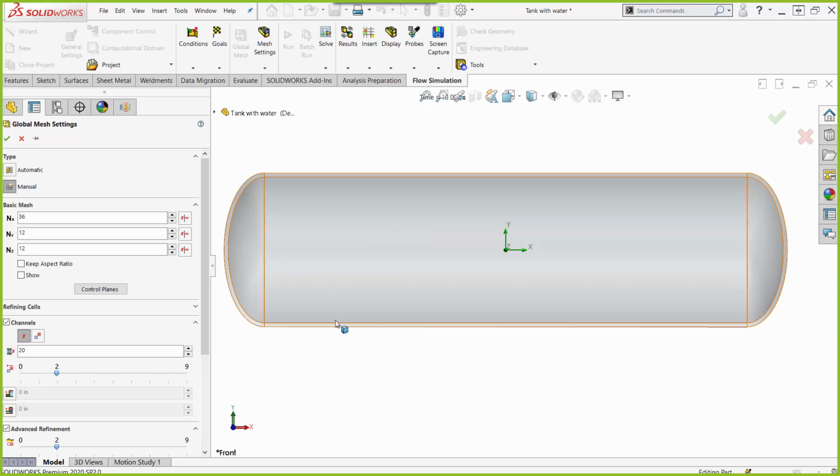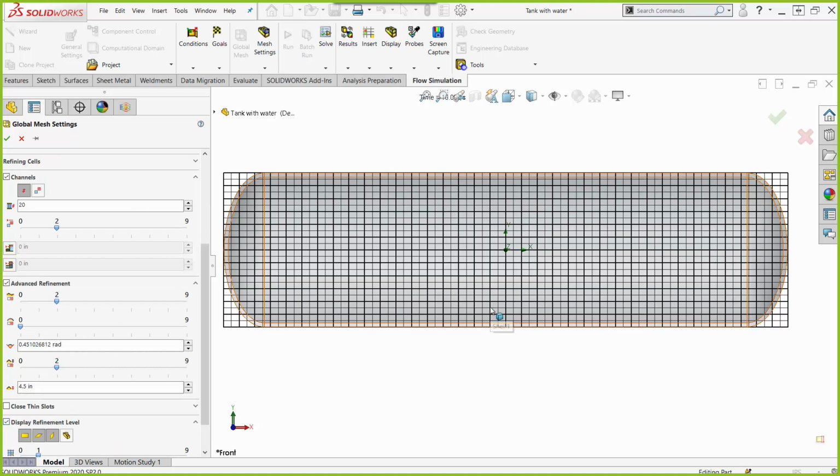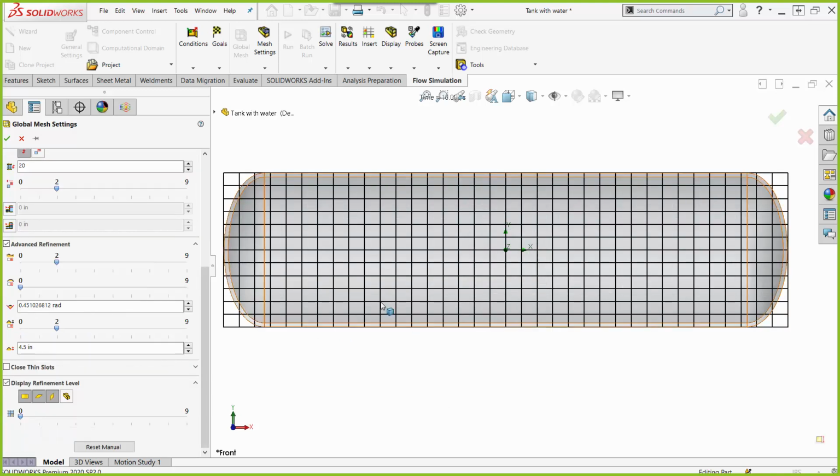So for accurate answers, I need a good representation of the volume of the fluid, right? That just seems logical. If I have fluid cells that are too large, I'm not capturing that interface or that free surface very well, and so I'm getting a very blurry, strange kind of result. So it is recommended that you do refine anywhere that there's going to be a fluid interface.